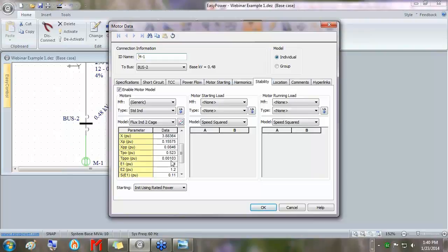And you'll find that this may cause your simulation to go numerical. I mean, we recover from it nicely in this dynamic stability package. We'll just tell you, hey, you have numerical issues, you need to lower your time step. And so all you do is go in, options, lower your time step. It'll take the simulation a little longer to run, but you have to cover for this condition.